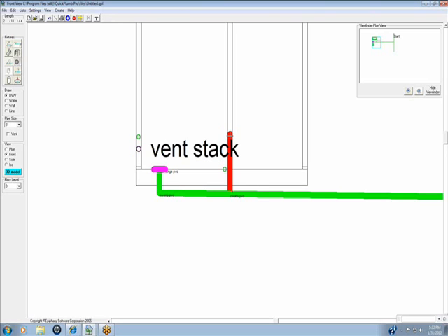With 35 years of plumbing experience, I'd say it would work in 10 feet. Some codes, like Virginia, I don't even believe there is a maximum. I think they like a toilet to siphon. When you think about it, it makes sense. But anyway, we have to work with what they tell us, right? You got to go by code.